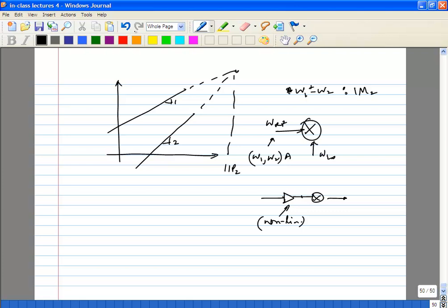Either one, right? Because if you put in 2 components omega 1, omega 2, you are going to get the fundamental gain times omega 1 and omega 2. So it doesn't matter which one you choose. Okay, of course the circuit is going to be symmetric. If you are given 2 components of equal amplitudes, it will be symmetric because they are so close. Okay, so now you can plot your IIP2.